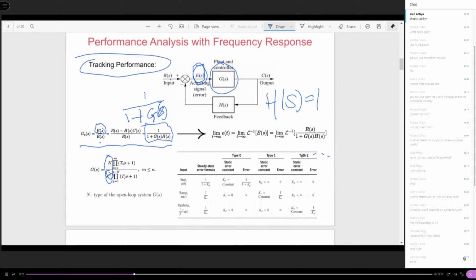Anytime, you need to make sure this closed loop transfer function is stable. Specifically, check the denominator of the transfer function to see where the poles are, before you apply the open loop information to find the tracking.